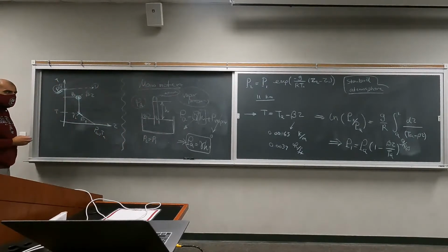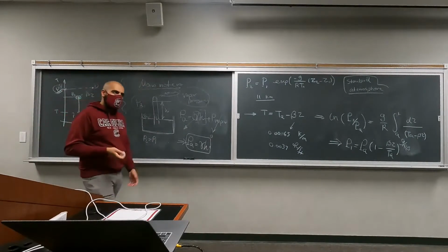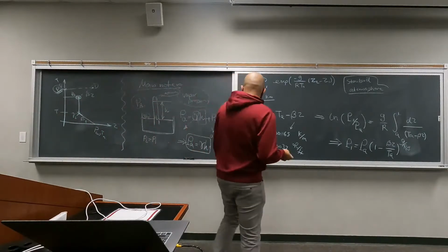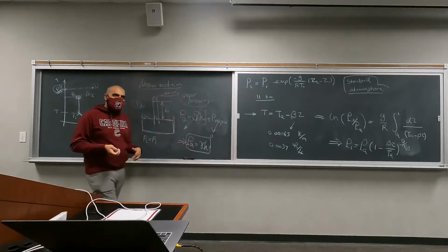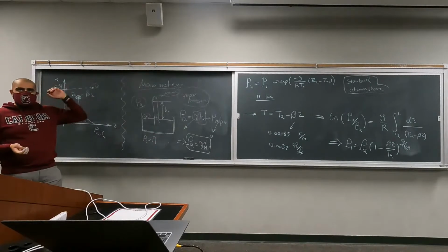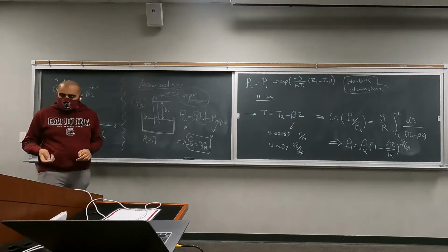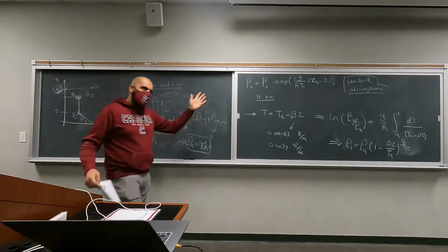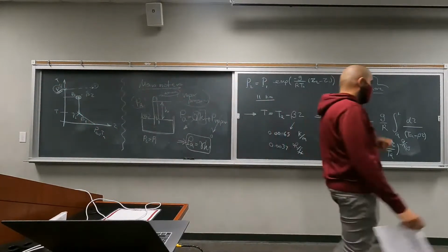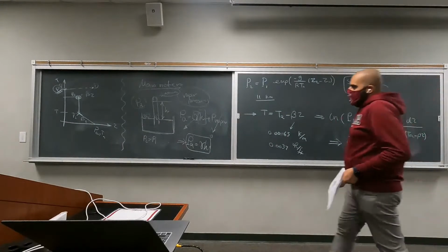That's very simple. Gamma for mercury is high compared to water. If you were to use water here, the height for atmospheric pressure would have been in feet, not in inches or millimeters. So we would need a very large, or a very long tube to be able to measure the pressure.